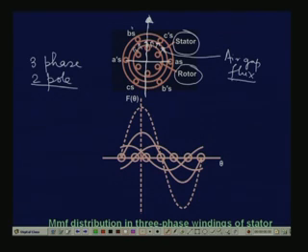Similarly, the BB dashed coil will have another axis, this kind of an axis, and the CC dashed coil will have this sort of an axis. So we have 3 coil axes spatially separated, in this case, by 120 degrees.